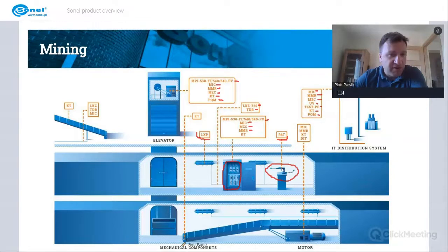And here we can find any faulty mechanical components by finding those overheating components with thermal imagers of KT series. And we'll find here also the motor. So something needs to power this transmission line. And the motor, as well as any other rotating equipment, we will check here insulation resistance with MIC series meters. We can check the continuity in the windings with micrometers, MMR series, and any overheating components, again, with thermal imagers, so KT or DIT series.